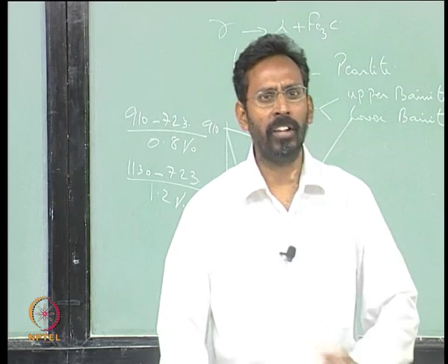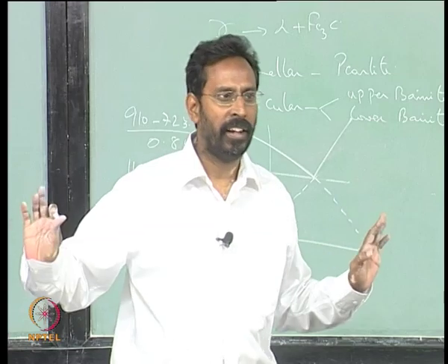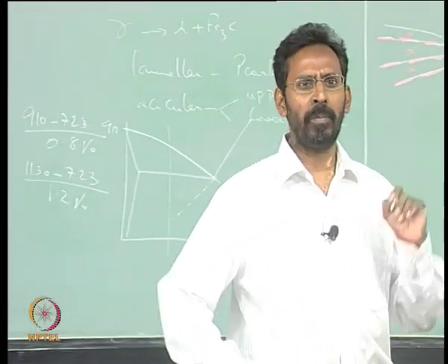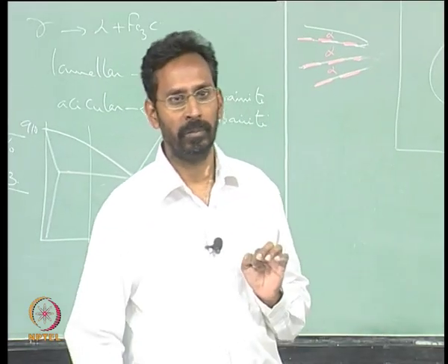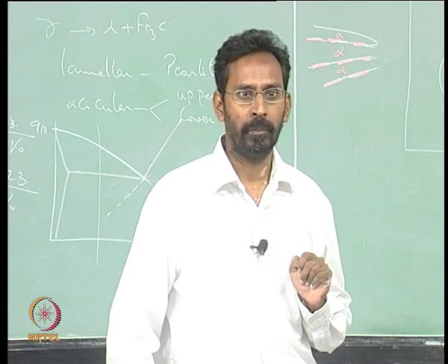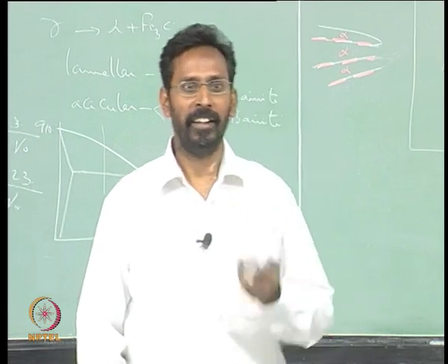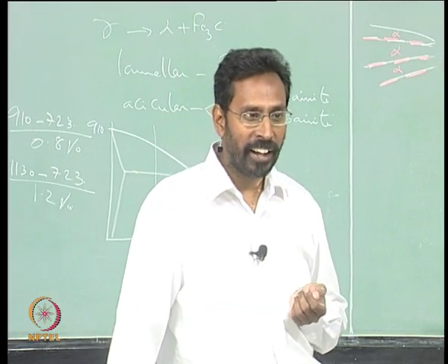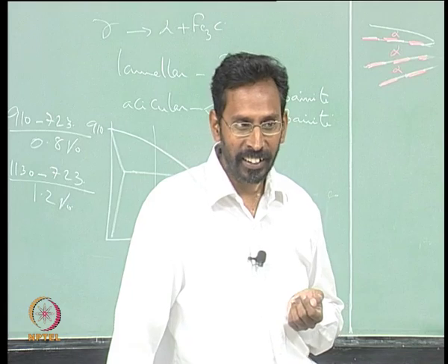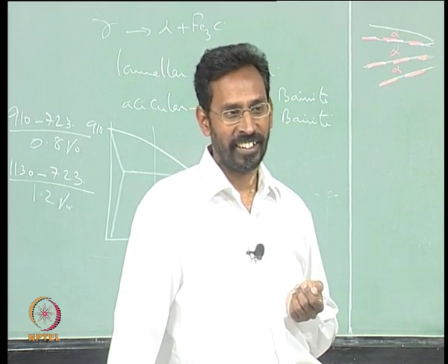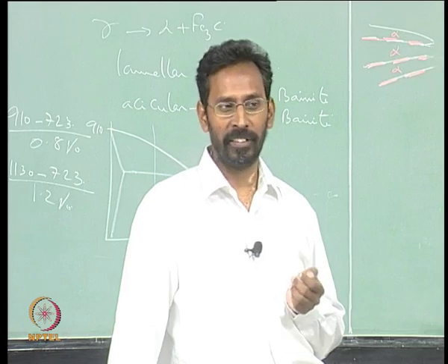Do not consider any alloying elements, nothing. I am not even concerned about the pro-eutectoid, simply 0.4 and 1.2. What would happen to the TTT diagram? Both sides cases, you try it. Till 0.8 it shifts to the right, yes. They do not observe the shift after 0.8.